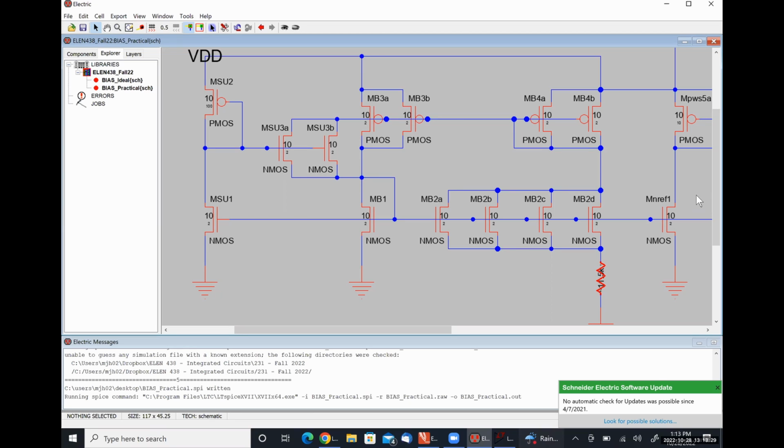I'm running DRC and it's showing me I have all these unnecessary pins. Yep, just delete them. I was trying to delete them. That's the exact same issue that Sam was having. Ultimately they shouldn't really matter too much, but just hit F5 and hit OK, then look for the next one, and it will highlight it for you. Then F5 again, and just keep doing that until you get 0 errors.